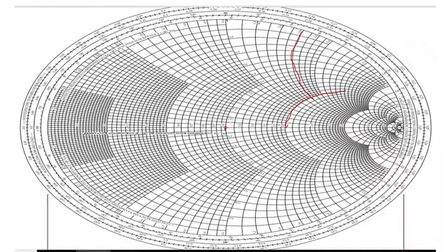Yeah, this is it. You're supposed to find the VSWR circle. If it would have been the shunt configuration, you would have plotted the VSWR circle and found out the admittance. Please note this is a series configuration. We will still be working at the ZL point, not the YL point. To find the VSWR circle, how do you do it? I hope you remember. Keep the center of the compass at unity gain. This point, this is your radius. I hope you remember this. This is the radius, and then plot the circle. So what happens when you plot the circle?